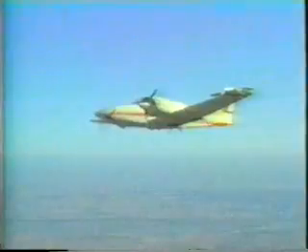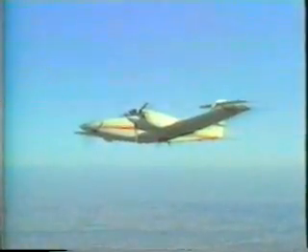Another application of VYSE is in connection with the single-engine service ceiling. This ceiling is the maximum density altitude at which VYSE will give you a 50 foot per minute rate of climb with one engine inoperative. The single-engine absolute ceiling is the maximum density altitude an airplane can reach and maintain on one engine. Now that we've discussed the theory of engine-out flight, let's look at some practical applications.